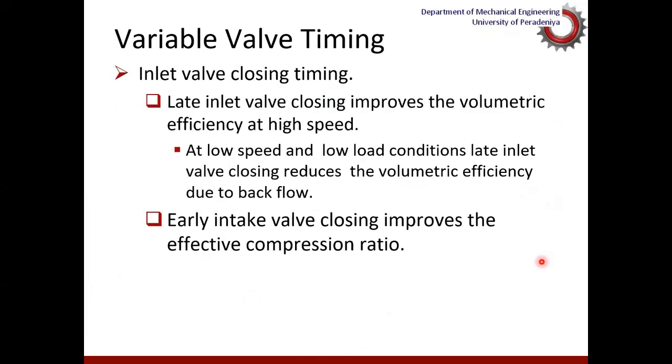Early intake valve closing improves the effective compression ratio. When you have the valves open, when it comes to calculation of the compression ratio, the effective compression ratio includes some of these areas above the valve. So these are open. When it comes to calculation of the clearance volume, some of these areas also need to be considered.